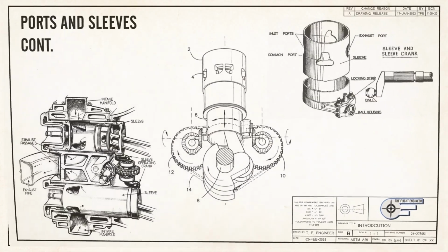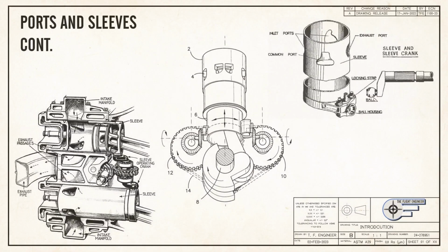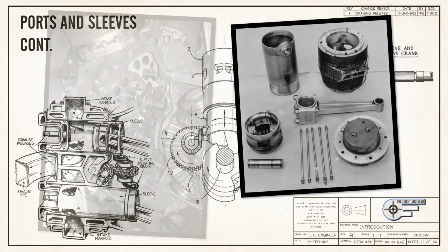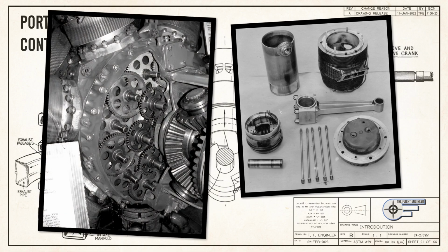An evolution of the cylinder port concept leads to the sleeve valve design. Engines with this valve arrangement use cylinder ports, but instead of them being opened or closed by the piston, an intermediate sleeve performs this function. The piston translates inside the sleeve, which itself translates and rotates inside the cylinder's bore. When the ports in the cylinder's bore align with the ports in the sleeve, fluid can flow in or out of the cylinder. This design combines the flow performance of ports with the controllability and precision of poppet valves. Unfortunately, this comes at the cost of great complexity.